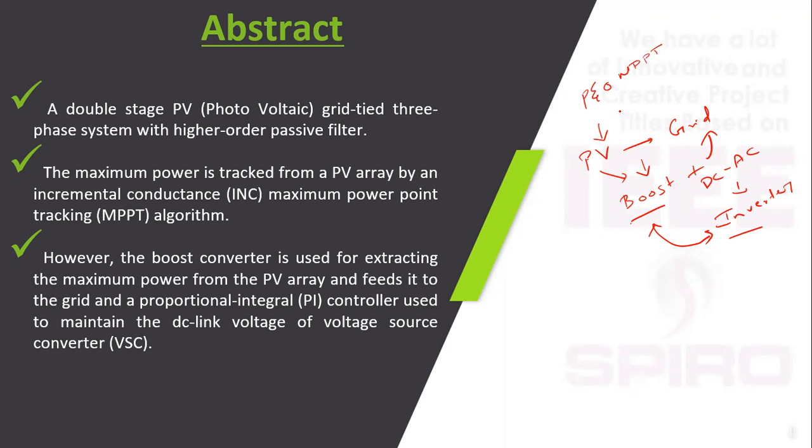In this proposed concept, instead of P&O MPPT, the incremental conductance method is used, because for the dynamic changes in input solar irradiation to the PV, incremental conductance is good for tracking. It will correct the false tracking.